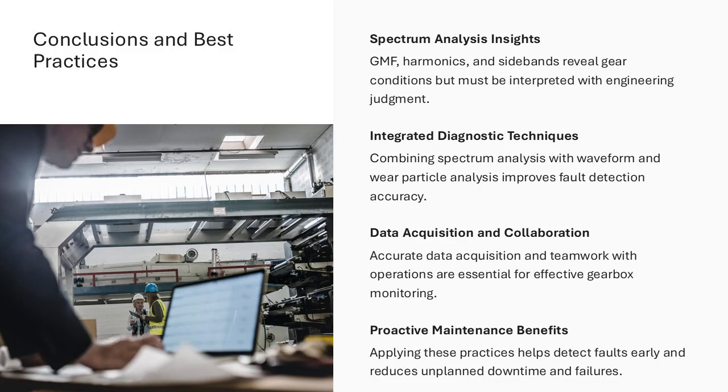Diagnosing gearbox faults using vibration spectrum analysis is a powerful but nuanced process that requires engineering judgment and experience. GMF, its harmonics, and sidebands provide essential information about gear condition, load effects, and mechanical integrity. However, no single spectral feature should be interpreted in isolation. Best practice involves combining spectrum analysis with complementary techniques such as time waveform analysis, time synchronous averaging, and wear particle analysis. This integrated approach improves fault discrimination and reduces the risk of misdiagnosis.